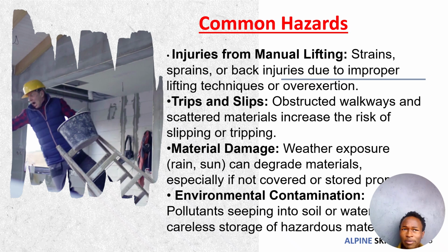That's materials like cement. Using cement again as an example, we all know that when cement comes into contact with water, it hardens. It starts its hydration process. So when storing materials such as cement, you have to make sure that you store them in a cool, dry place, such that by the time they are put into use, the quality is still desirable for working on.